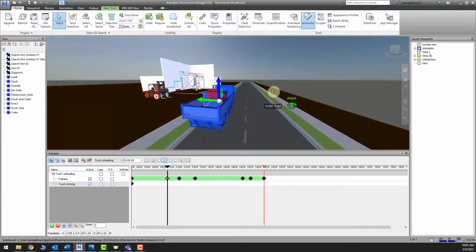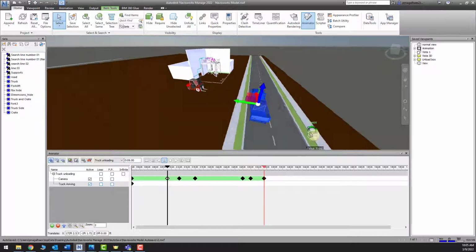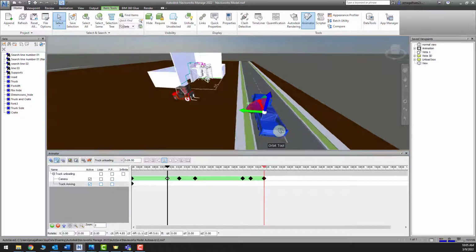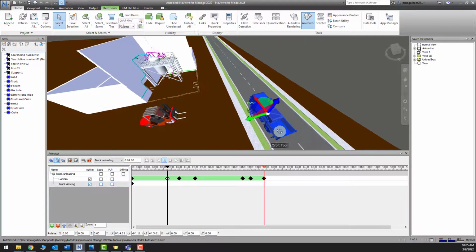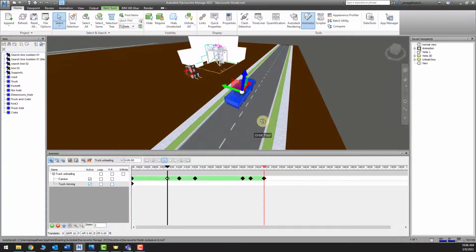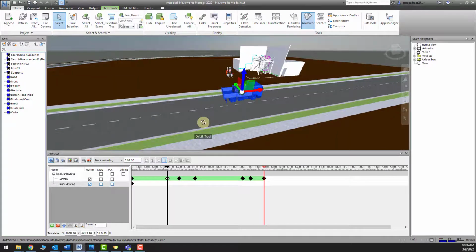So when we move the truck, you can see that the road did not quite follow. It's not as straight. It's not aligned with the move arrow. So now we will be moving a little bit to the right. And we can select the rotate, and we can rotate a little bit to the right as well, just a tiny bit. And now let's move this a bit forward. We need to select the move, and we'll move it a bit forward, and maybe a bit more to the right. To orbit, use Shift and the middle mouse button to use the orbit tool.